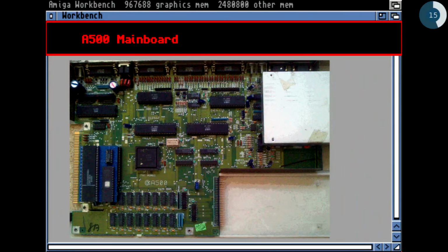Okay, that's the main part of the Amiga 500. What we see here, on the left side, is the CPU. It's a DIL package, 64 pins. It's a 68K processor. Then here is the ROM. Actually, that's an extension I built myself for the new Kickstart. So that's the ROM. Here down below we have the dynamic RAM.